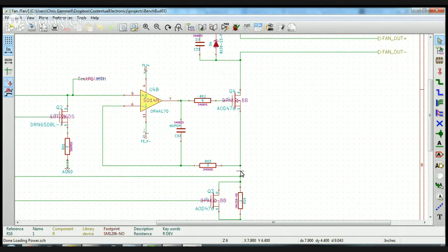Sorry. So if we want 4 volts here to match 4 volts here, this would have to be 8 ohms then. The only downside is if you go up in ohms, we start becoming subjected to power problems, because you think I squared R, right? That's power equals I squared times R. If you have 8 ohms here now, 1/2 an amp squared would be 0.25 amps times 8. That's 1/4 of 8, so that's 2 watts through this resistor. So we might have to do resistor stacking or something similar like that. We'll have to do that calculation at a later date, but if we do want to get more fine control, we'll have to deal with that.